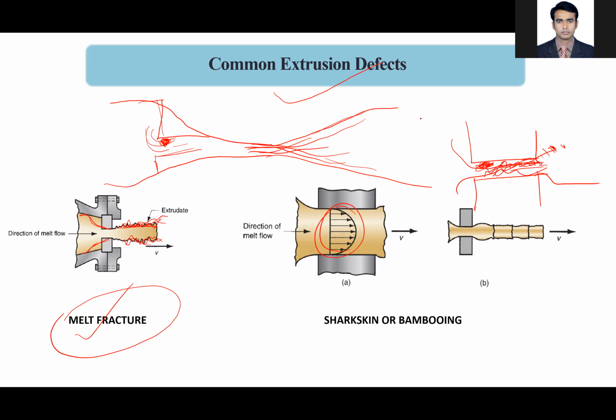Yes, we are getting the back pressure, that is right, and that is also included in the calculation. Actually, I did not show that, but if you read this book, you'll see that the total volume flow rate getting out of the die is equal to two parameters: Q equals QA minus QB. QB is the backflow due to the back pressure.